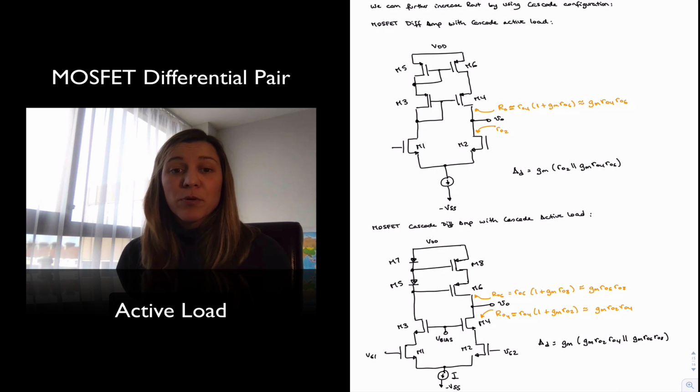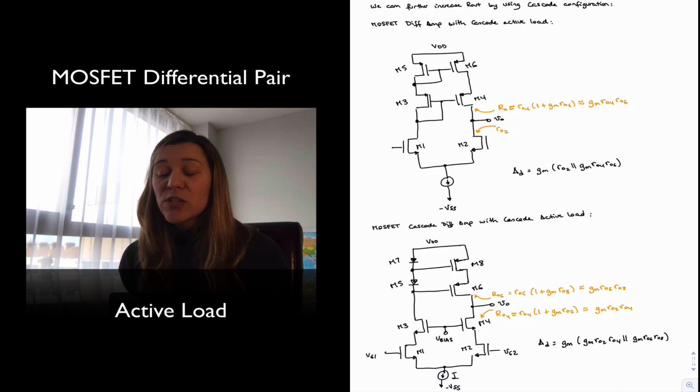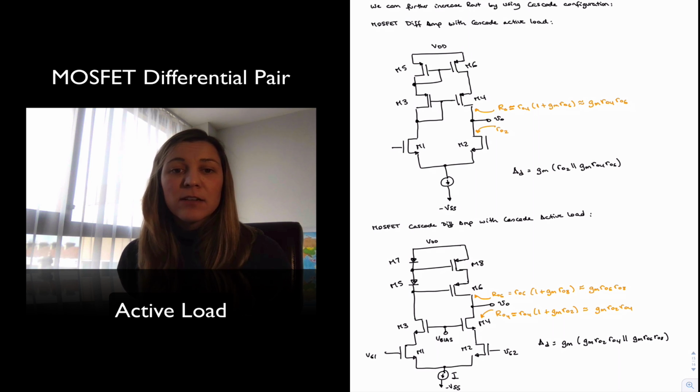We want it to be as high as possible because the idea is that then we're going to connect the amplifier using negative feedback, and we're going to decrease the gain, make it virtually independent of the open loop gain and mostly dependent on external components. But in order for that approximation, that independence of the open loop gain, to be close to reality, we need for the gain to be as high as possible. And that's why we care about building an amplifier with a very high gain as opposed to a very accurate gain. Thank you.